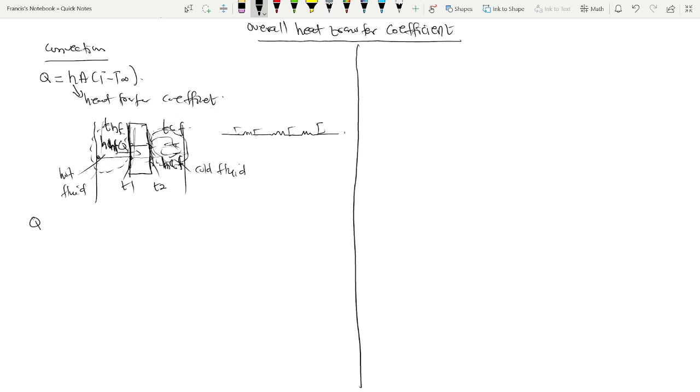And from our previous video, we said that the current is just like our heat transfer, and our resistance is our thermal resistance. And the potential difference causing the driving of the current in this case is our temperature difference. We realize that the current passing through this resistor will be the same current passing through this, the same current passing through this.